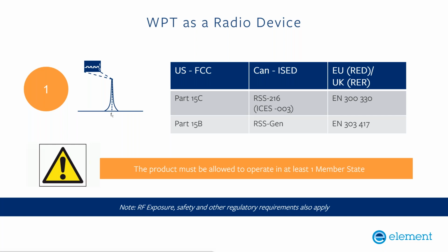The detail of whether it's communication or just an ISM device is in the RSS 216 standard itself. Therefore, if you're designing a product for the Canadian market, that is the standard that would apply for all types of WPT, irrespective of the theory of operation.